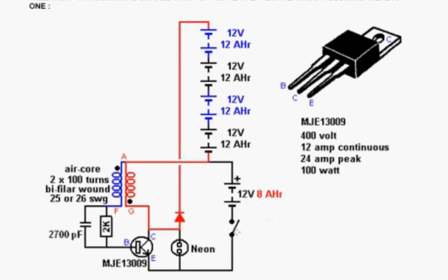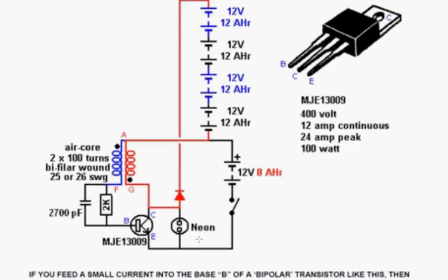It has an on-off switch if you want to be fancy. You don't have to have one. You can just connect to the battery. And it has a neon, which is effectively a spark gap. This particular neon spark gap is typical. It's called a neon bulb, and it triggers somewhere between 90 volts and 110 volts.